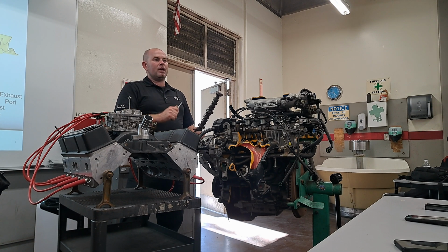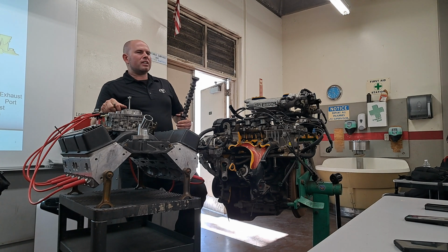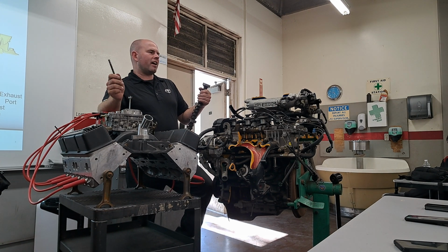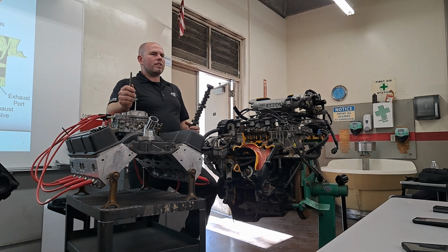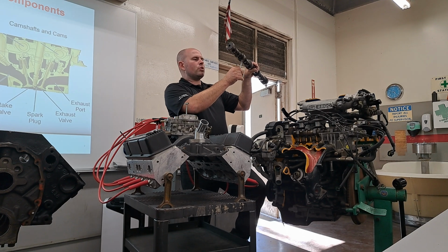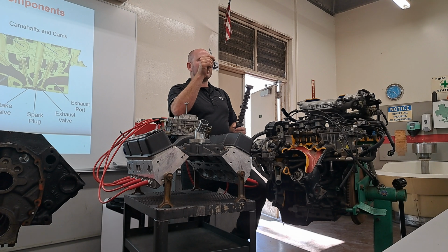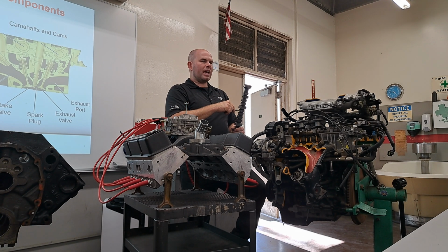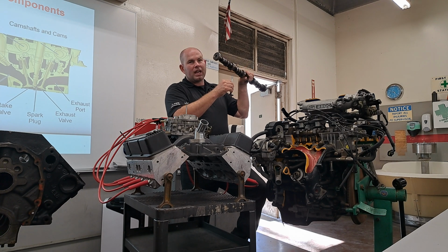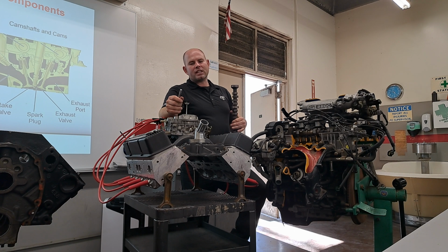The negative, though, and I'll tell you, some of those German and Italian engineers are pretty smart, is this. Now you've got double valve adjustment to worry about. So there has to be a precise adjustment between these two. You can't have them necessarily touching because when the valve gets hot, now it's pushing up against the cam. The cam doesn't move, so it'll actually push the valve open a little bit, and now you have a valve that's not seating all the way. It's kind of trippy, huh? So that's the main purpose of the valve adjustment.